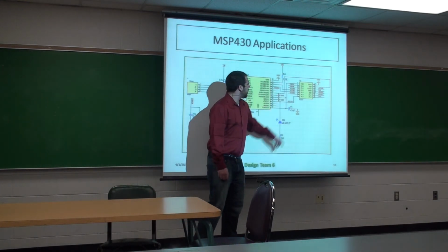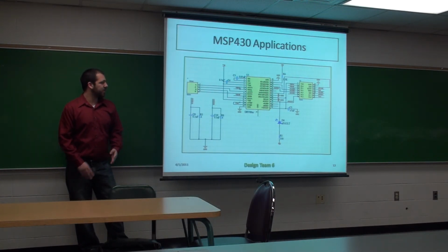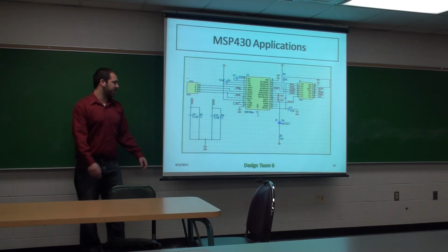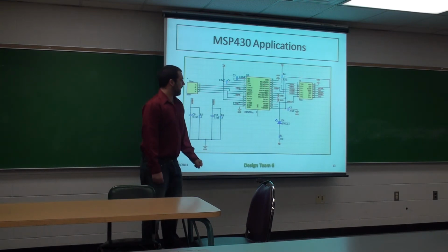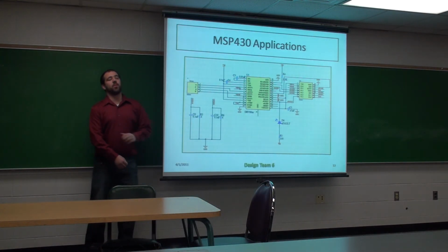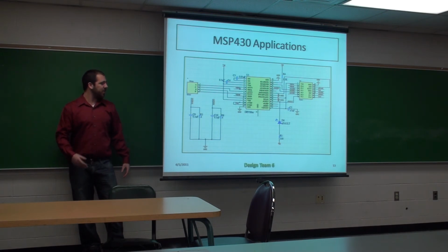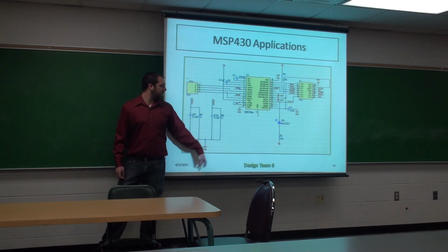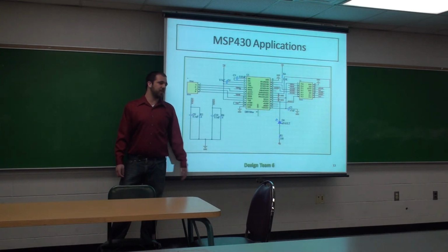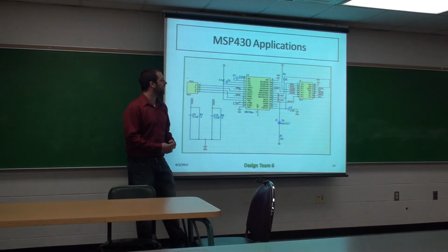Mode 0, 1, and 2. 0 is half stepping, 1 is 1/8 stepping, and 2 is 1/16, and you can mix them together to get up to 1/32. We have nFAULT. What's really nice about this chip is if your temperature is getting too high, or your motor's not moving but you're trying to tell it to, the nFAULT condition will go high. You can throw an LED to it, and it'll shine so you know that your motor's got a problem. You can also feed it back into the microcontroller and then handle that error also.